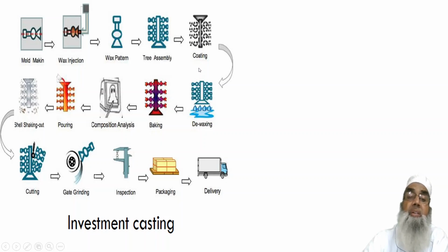They are dipped in the ceramic slurry. A thin layer adheres to the surface of the pattern, and after achieving sufficient thickness of this refractory material, they are heated so that the slurry gets bonded and the wax material is taken out, and therefore they make the cavity.